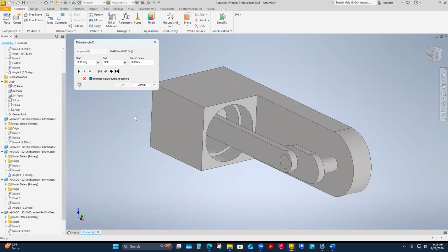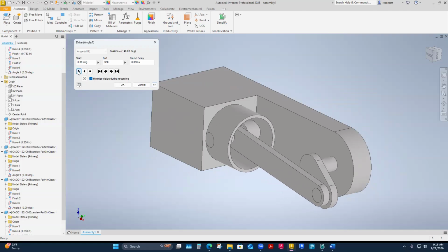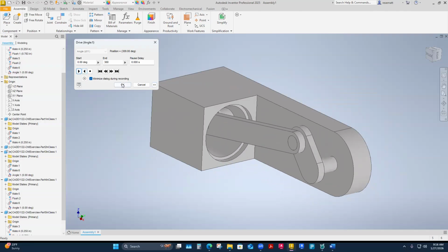The other thing it can do here. Because we made it, that's why. The only reason that moves is because there are no conflicting constraints here that don't allow it to move, right? I'm actually only driving that one constraint. But if you had constraints that don't allow that movement, they won't animate that way. You have to delete constraints. So really they used very minimal constraints to do this.